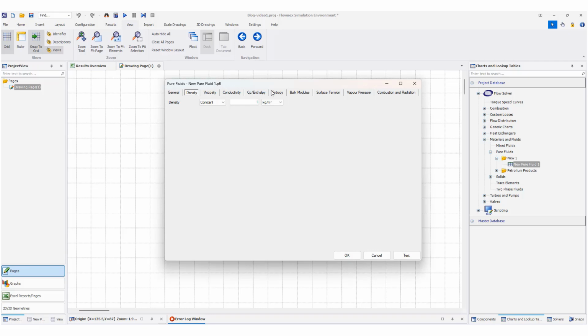Now I can start to add the material properties here. Every material property could be constant or be defined in terms of some parameters, as in tabular form or in an equation, or I can use a script for that. For example, here I use a density of 900 kilograms per cubic meter. I want to have my viscosity in terms of parameters instead of being constant, so I can use an equation for that as a polynomial.